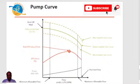On a pump curve, instead of flow, you can see capacity, which is still the same thing. So you can see pump capacity on the horizontal axis, and pump head or pressure on the vertical, in unit time. That head is the differential pressure, the difference between the pump outlet pressure and inlet pressure, in terms of liquid column.